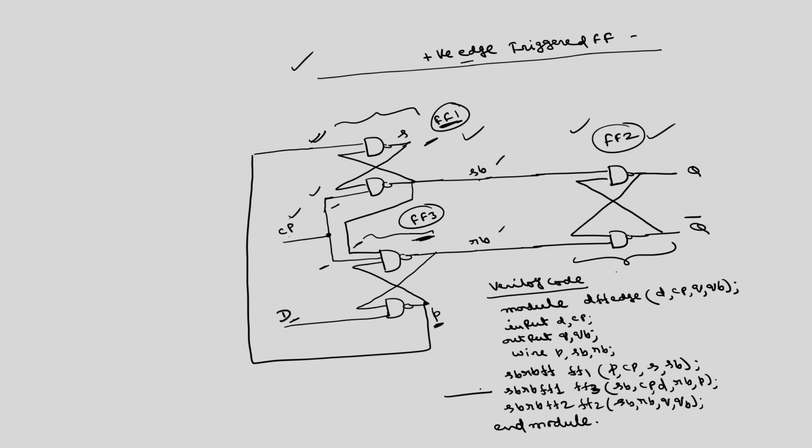So, the code corresponding to this flip flop, I am calling as this is FF1, this is FF only, this is also FF only, but this is FF1. So, to derive this FF1 from this 2 input NAND gate, basically here you should have only 2 input NAND gate, but we have 3 input NAND gate. Suppose if I want to derive a 3 input NAND gate from 2 input NAND gate, this is ABC, I require ABC bar.